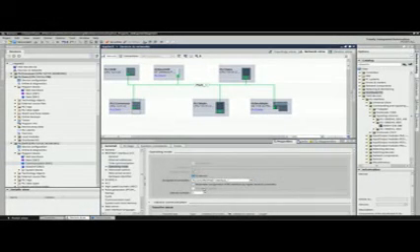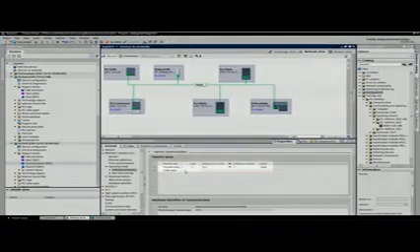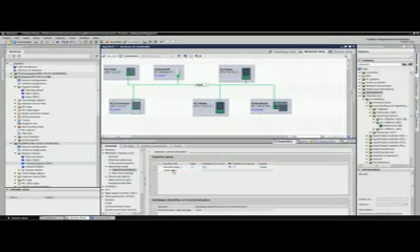And in order for the two now configured I/O controllers to communicate with one another, you have to create transfer areas. Once this is completed, the actual data exchange will ensue. These transfer areas are allocated input and output addresses on both sides. Once these addresses are assigned, they will serve as hardware I/Os from the user program of the controller.